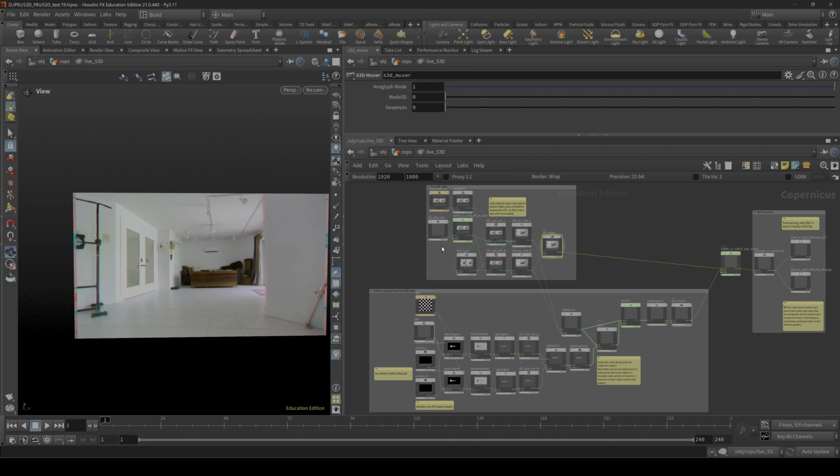It's doing it over for left and it's doing it over for right, in like a loop in one node. So this is really neat that I can do multicam like this. The problem is that if I had multiple channels in my left, like alpha and different AOVs, you can't nest cables. So I'd still have to make a ton of nodes to deal with this. So if you have multiple cameras and multiple channels, this is a setback because currently, and I'm not sure if they'll address this in the future, you cannot nest cables.